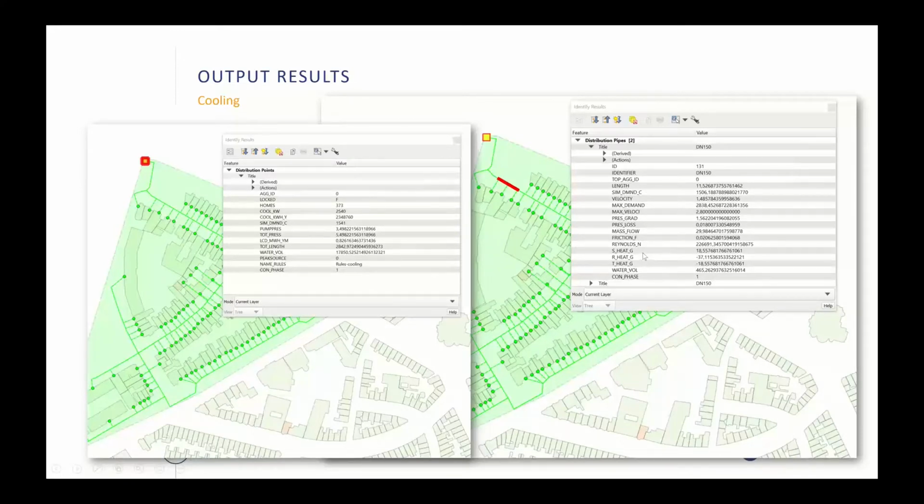And another difference is we don't have any heat losses in the pipe. Actually, because of the friction, we have a small gain in heat. So that is also indicated here. We have a small gain in heat, which is actually negative in this type of network because you want to use it for cooling. That is also calculated and indicated here in the list of calculated parameters.